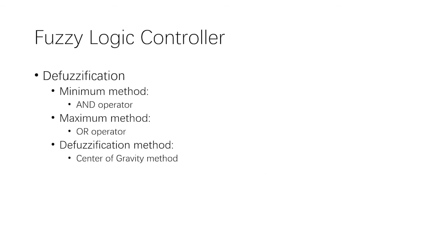And in the defuzzification part, we use the minimum method as the AND operator. We use the maximum method as the OR operator, and use the center of gravity method for defuzzification.